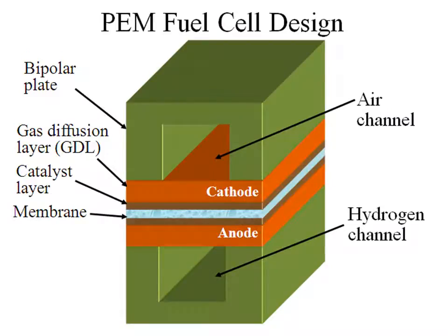Okay, so here's a good visualization of what's going on in the fuel cell. The green here are the bipolar plates. So imagine the plate is actually bipolar, which means that a single plate would have both the air and hydrogen channels. So you could almost imagine this being stacked, one on top of each other. In this case, we'll show air going through the air channel, and then there'll be a gas diffusion layer. This is a porous carbon material. We'll show it in the next slide.